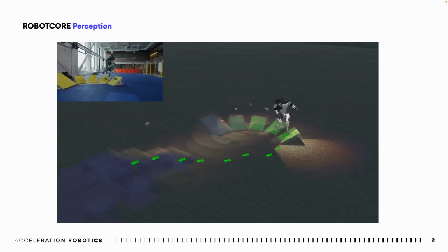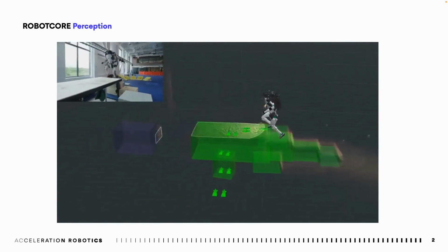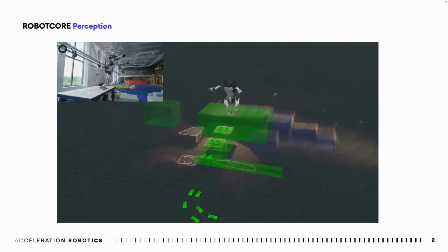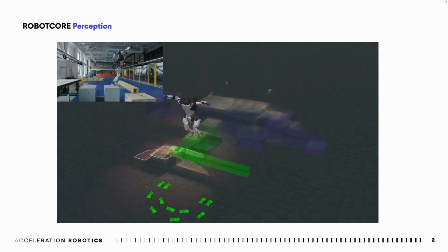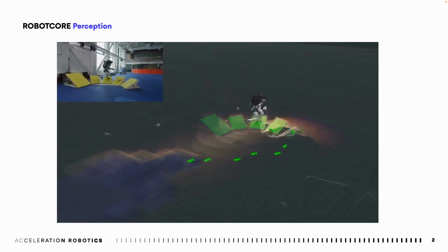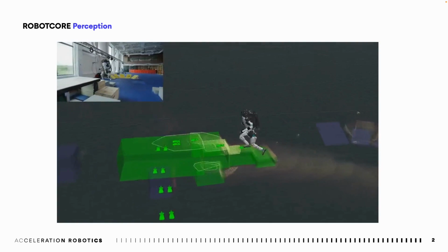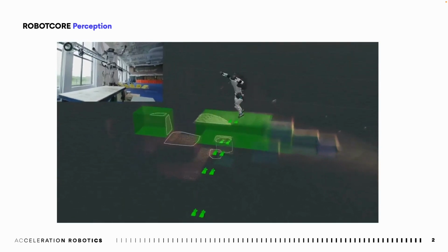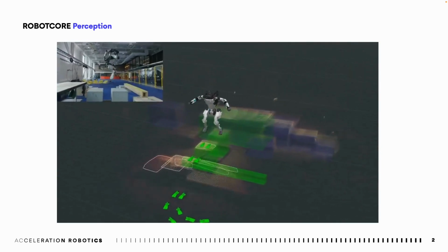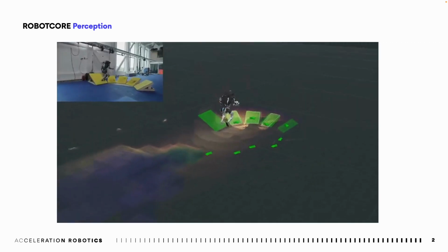The point cloud is a large and dense collection of range measurements which needs to be processed at the edge directly in the robot for smooth behaviors, reducing any latency from the sensors and all the way into the actuators. By leveraging hardware acceleration, Atlas's perception extracts surfaces from this point cloud, which are then used to plan actions in the order of tens of milliseconds, all happening on the edge.